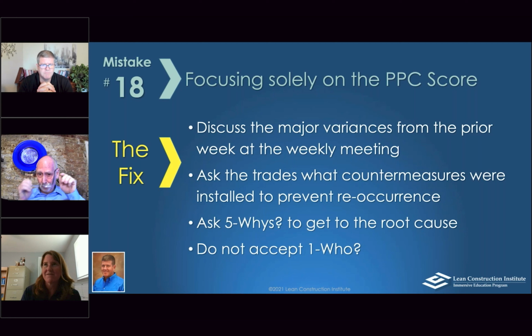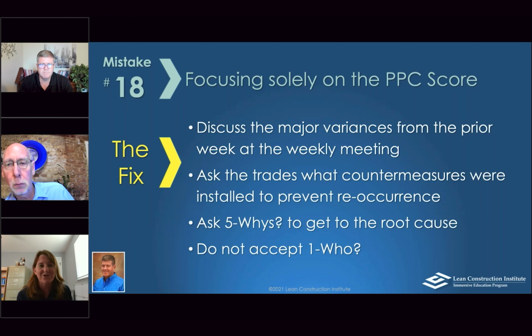So as far as the plan, it depends on what you're talking about for make-ready planning. There is the identification of the constraints in a weekly meeting. I would suggest setting aside about 10 minutes to say, here's what the vision is, let's talk through it. But also part of that is doing the update of what has happened since last week, what's been cleared, what's been taken care of, and what we now have to follow up on. If you're in that weekly meeting and trying to make it about 10 minutes, plan for that so you don't go through every single constraint and have a conversation with the champion about every single one of them, and that'll be your whole meeting.